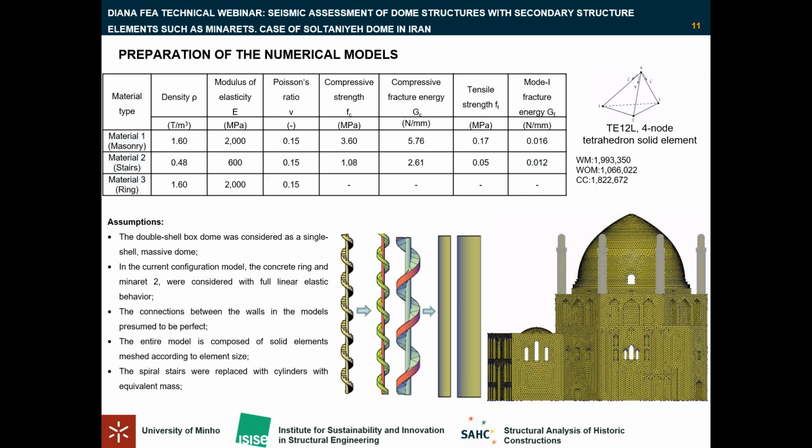In the framework of this research, only vertical gravitational load or self-weight and the seismic load with horizontal pattern proportional to the mass of the structure defined by Eurocode 8 was adopted. In order to define the boundary condition, the translation of the structure in all directions was assumed as fixed.